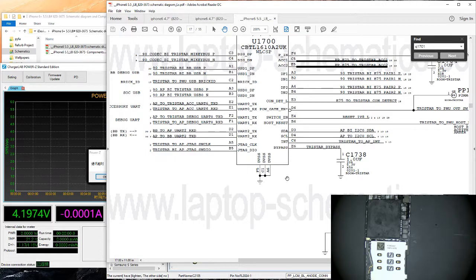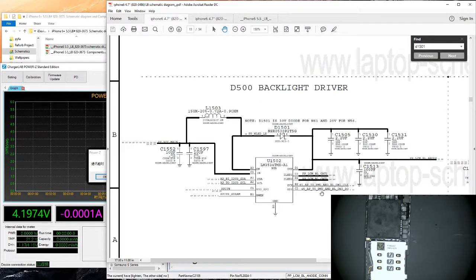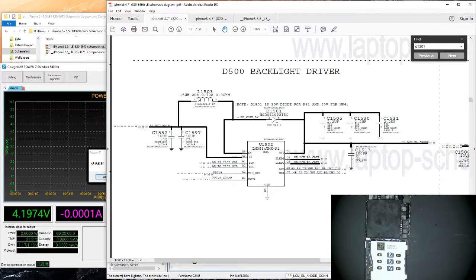When we go to the schematic, here it is. Look, I did so much prep work today, making sure this is gonna be quick and easy, quick and dirty. So here are those two caps that we pointed at, VCC main. They feed into this side of a large coil. That coil is just storing energy for basically transforming up into 20 some odd volts. Goes into this side of the diode and this side of the chip, the boost driver.